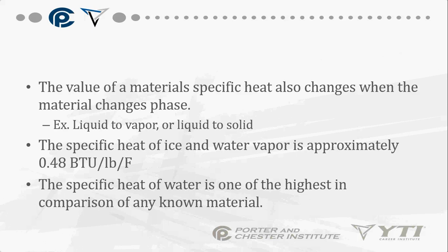But let's use an oil burner for a minute. We have a nozzle rated at 0.50 gallons per hour. That 0.50 is going to put out X amount of BTUs, right? What if I raise that pump pressure, say to maybe 125 PSI?